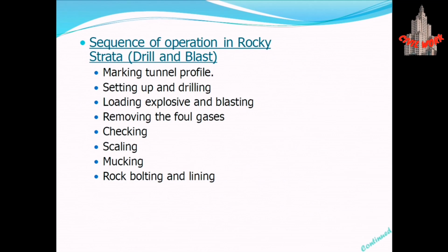Moving further, we have the sequence of operations in rocky strata: drill and blast, marking the tunnel profile, setting up drilling, loading explosive and blasting, removing the foul gases, checking, scaling, mucking, and at the last rock bolting and lining, which is for the stability of the tunnel.